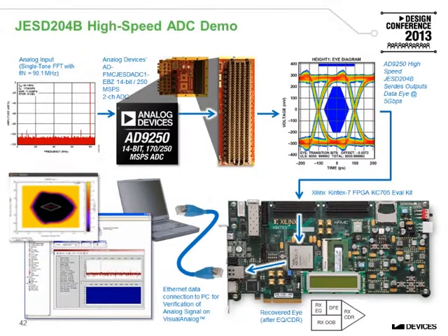This slide summarizes the iSCAN example. This whole demo setup runs the Analog Devices reference design, which includes the Xilinx Logic Core IP JESD204 core, and streams converter samples over Ethernet to VisualAnalog, where the data can be examined with a powerful analysis tool with a user-friendly graphical interface.